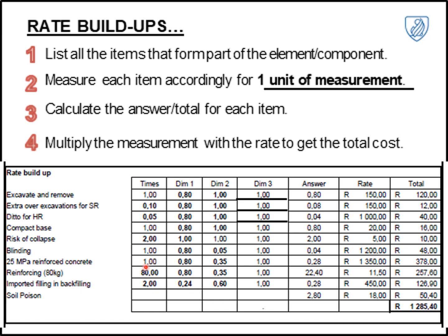We've got our reinforced concrete, which is only one component that we're using, but it's 0.8 meters wide and 350 millimeters high, times only 1 meter to get to a 0.28 times the rate per cube. Similar to our reinforcement, we've got 80 Rand that is then applied per cube. So it's 0.8 times 0.35 again to get to our factor that's then times with our rate.